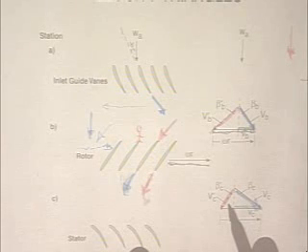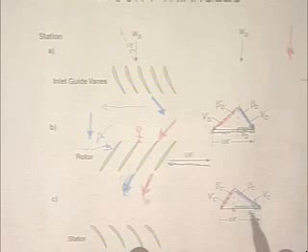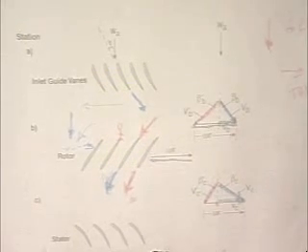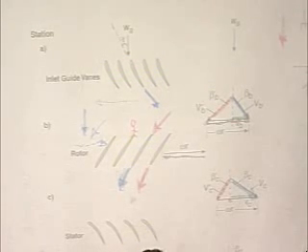That vector is this one. Then what I care about is this tangential component of the stationary frame velocity. So to get back to the stationary frame, I add back on the rotating component. I get the total flow vector, which you now see has more swirl. So this is a compressor. It's added swirling kinetic energy to the flow. Yeah?